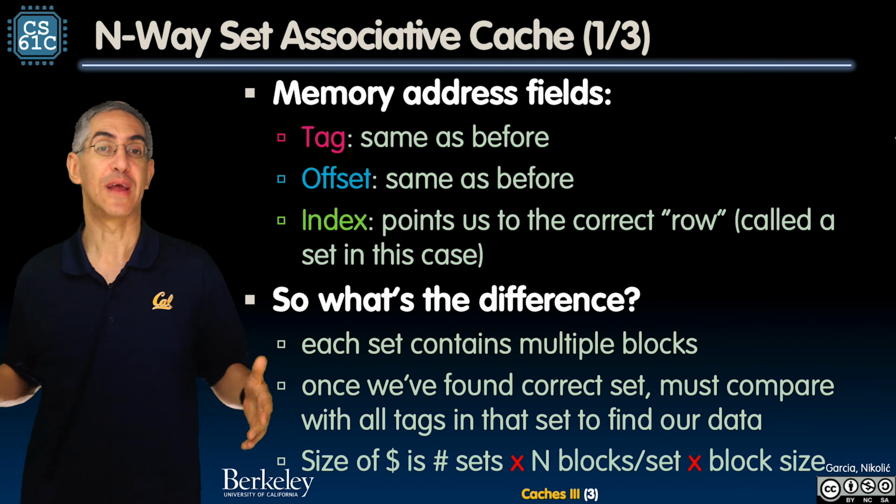So if I only had, let's say, a set that had 1 block, and I were copying from 0 to 4, I wouldn't be taking advantage of my cache at all, because I'd be kicking it out. Here's 0, and then here's 4, and then here's 0 and 4, and I wouldn't ever be making use of it. If I were walking along a really wide block, so my cache is small but wide, and I were streaming across, copying from one array to the other, a very common piece of code, duplicating an array, I'd be killed if I weren't able to somehow capture both the red areas. If both of them were blue, I wouldn't be able to have both blue in my cache at the same time. If you imagine a really big one, that's terrible.